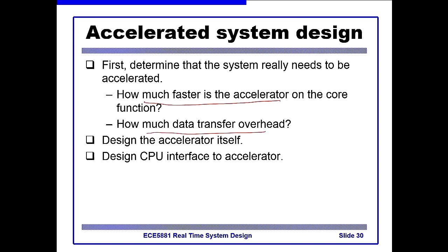Is there a large amount of data to be communicated? So we need to profile the system. So you run a profile, you work out what percent of time is being used by a particular function in the software, and then you start targeting that function. If it's 90% of the time being used in this one block of code, then that's a good candidate.